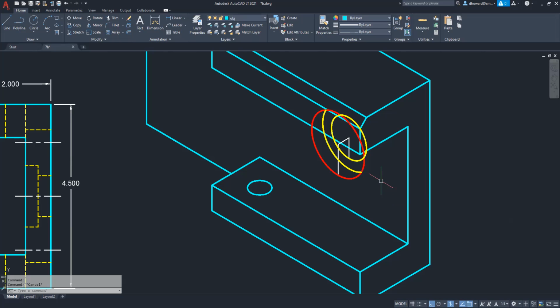But before I do that, let's make the exit hole. This 1-inch hole begins on this surface here, and then it exits on the back surface. For the back surface, we could copy from this center point to the back thickness, which is probably a good way to do that. I could also find that point by continuing this line and intersecting it with the center line of the back surface.